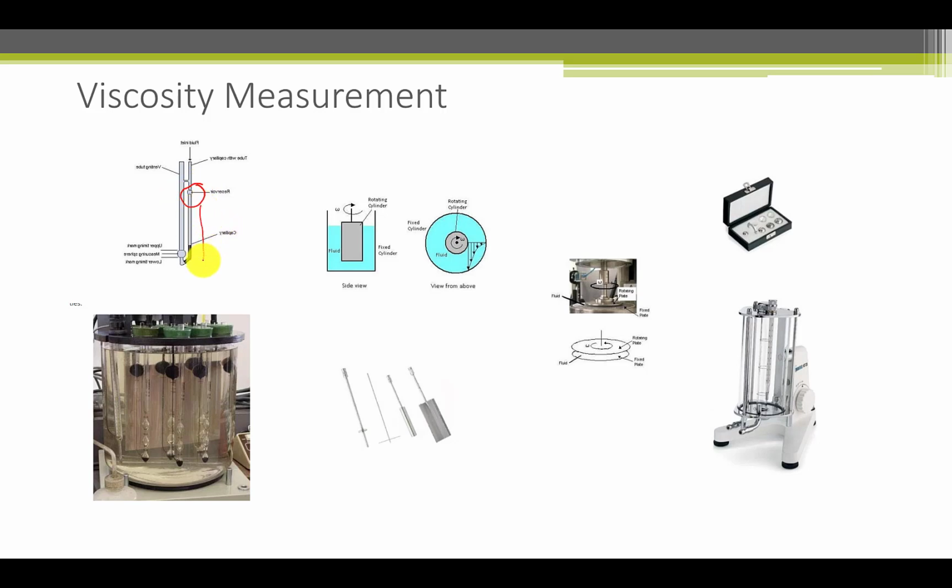And what it does is it drains down and ends up in this tube, and there's a little orifice. You basically measure the time of drainage, and that is being done here. This device, of course, is much more sophisticated because it's maintaining a constant temperature.